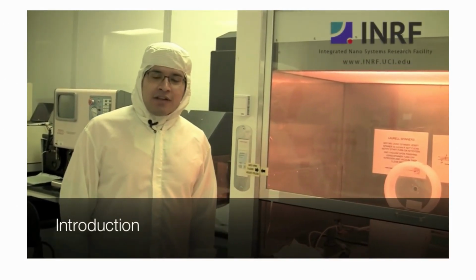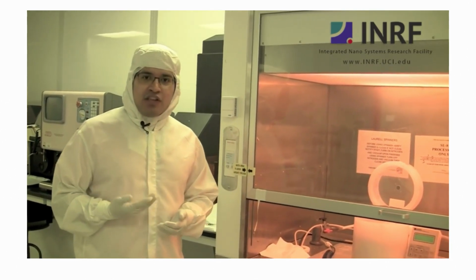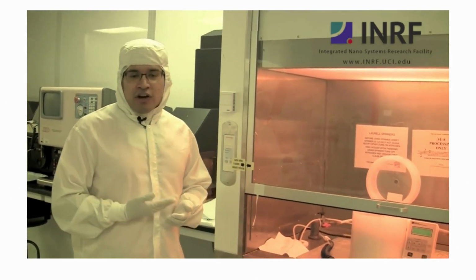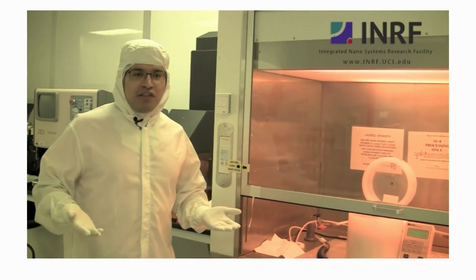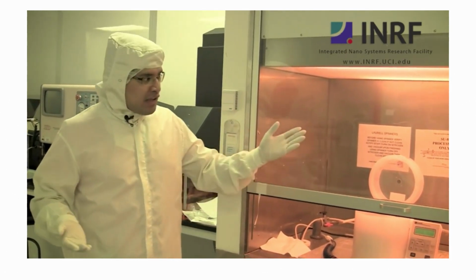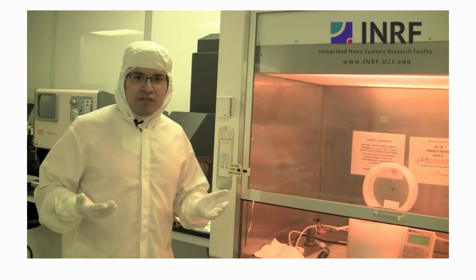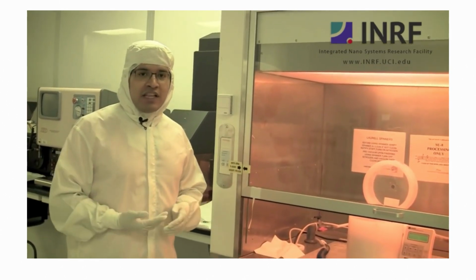Hello, today in this video we'd like to talk about photolithography. Photolithography is a process where you take photoresist, a solvent that is sensitive to light. This light spectrum is usually in the UV, so whenever you do photolithography, you're going to be working in this yellow room. As you can see, the room around me is yellow, and the hood is a little bit orange, but they both serve the same function, and that is to filter out UV light.